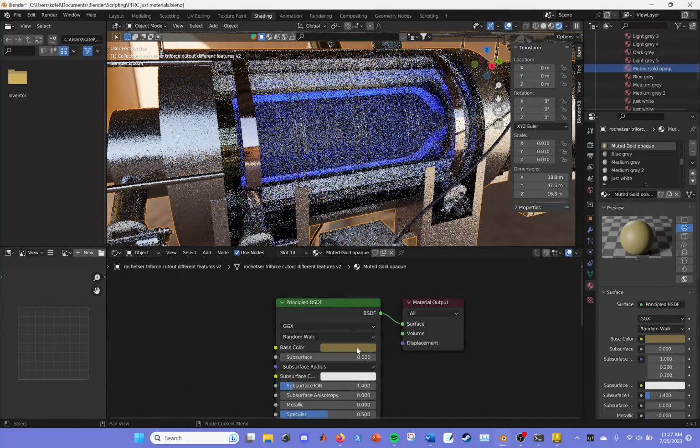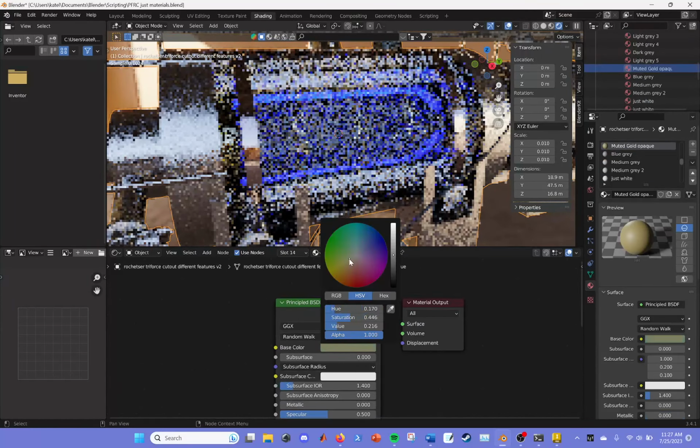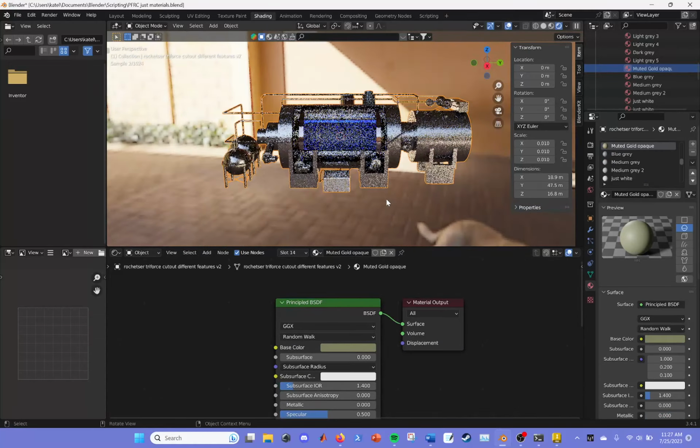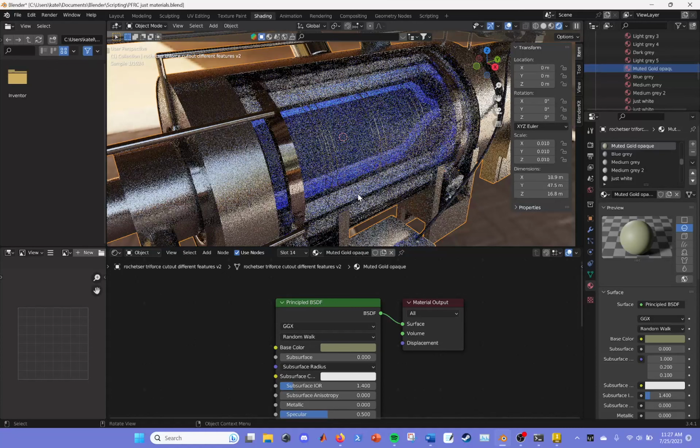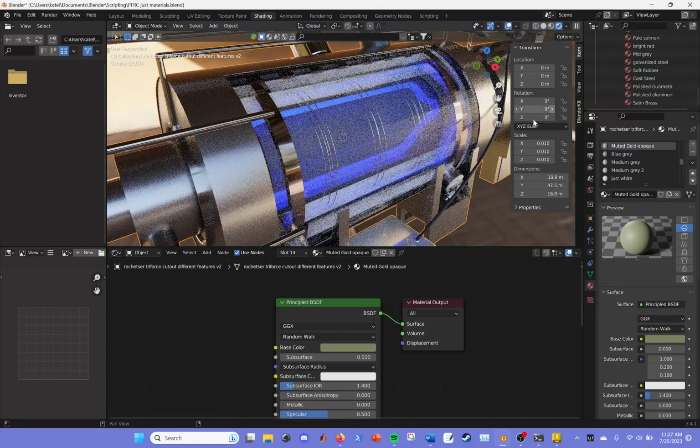Again, this is an OBJ file, which is why I was able to carry its materials into Blender. If I had imported an STL, it would be completely gray, and I would have to select faces by hand using the UV editing tab, which is something that you should avoid doing, especially with complicated objects.